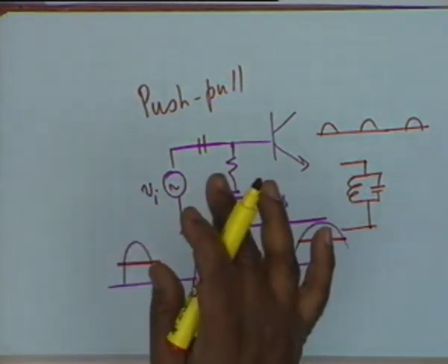At all other frequencies the impedance is low. So the voltage developed across this tuned circuit will be mostly that of the fundamental frequency, and that is how a sinusoid is restored.